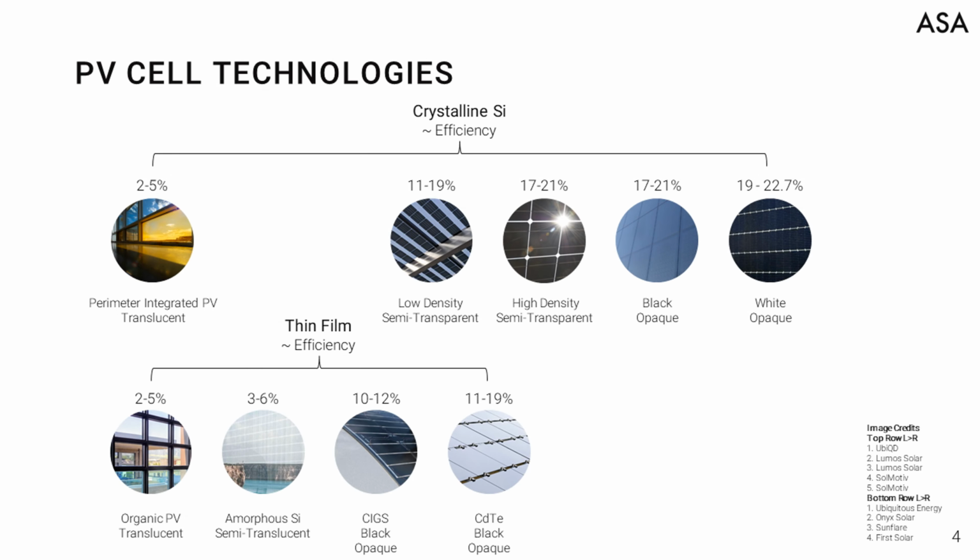Before we go too deep into all the integration opportunities, let's take a deeper look into solar cell technology. The two primary types of commercially available photovoltaic cell technologies are crystalline silicon and thin film. The crystalline silicon manufacturing process dates back to the 1950s and underpins all modern electronic technology. The silicon manufacturing process yields standalone circular silicon wafers cut from a larger cylindrical crystal. Wafers are processed into solar cells and individually laid up and electrically connected within solar modules.